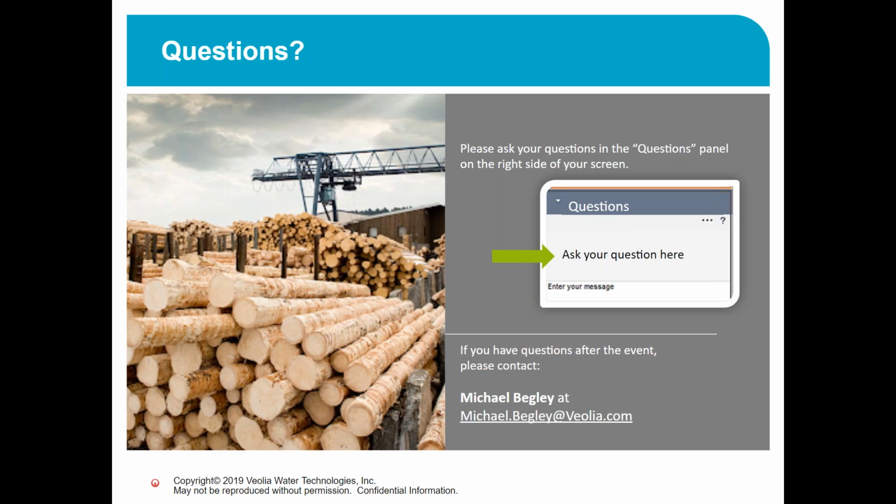Okay, another question we have here is, when considering ECRP or CRP, what would be the main drivers in considering between those two technologies? Normally the main driver, the reason for developing the ECRP technology, is for mills that have a high potassium content in the ash. The CRP process gets limited.